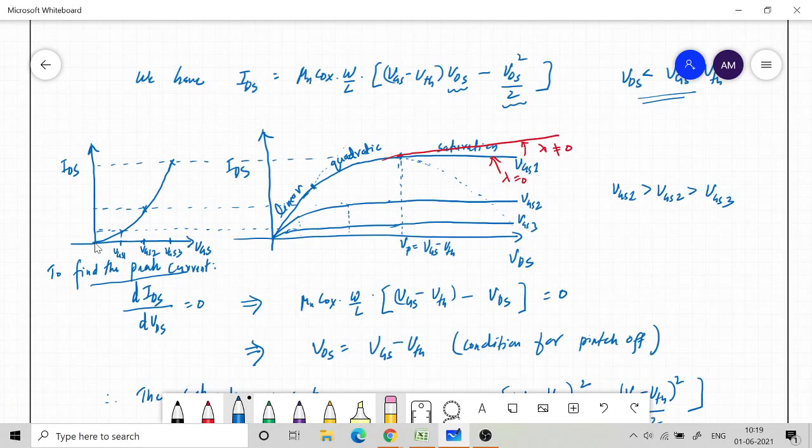That's what we initially drew, and then by using the SPICE directive we have specified a non-zero VTH, and when we have non-zero VTH, everything will be shifted like this. It will be 0 up to VTH, and then we have the curve like this. Okay, so this is basically our threshold.